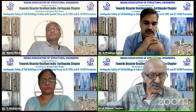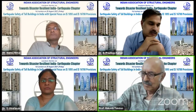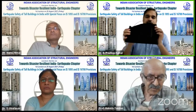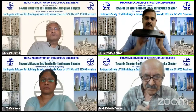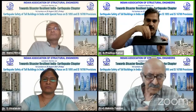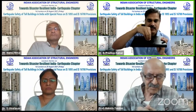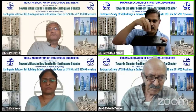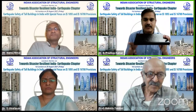Next question is, please explain the rigid diaphragm action. Rigid diaphragm action is something like, you can see my book. This is a rigid floor diaphragm. When we apply force, say earthquake force, which is an inertial force, it acts at the center of mass, and that force is fed to the lateral load resisting elements.